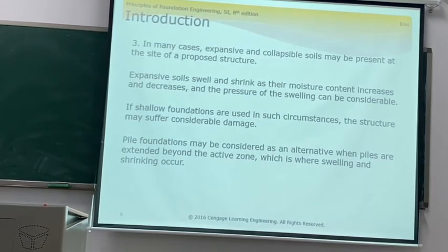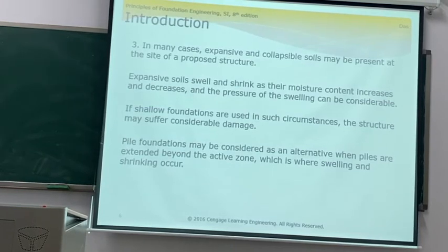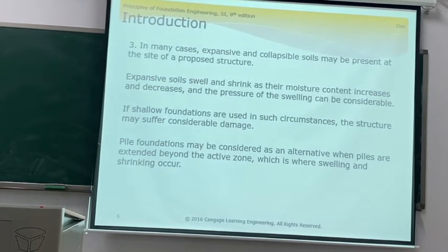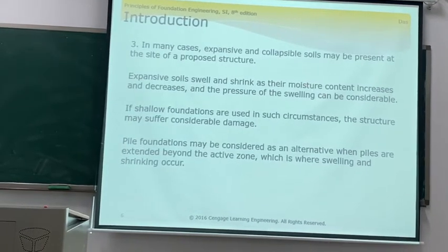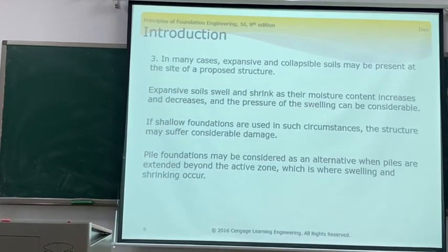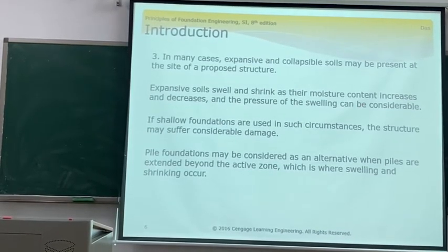When the water is out, it shrinks. So expansive soil swells and shrinks as the moisture content increases and decreases, and the pressure of the swelling can be concentrated.